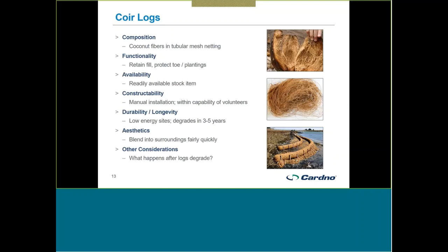I think one of the biggest considerations and potential downsides for their use in certain situations is their longevity. They are a natural material, and I've seen them last maybe up to 7 years, but they're looking pretty ratty. I think 5 years, maybe 3 years on the short end. 5 years is probably a pretty good rule of thumb about how long they'll last. And if you subject them, even when they're new, to high wave energy environments, they're not as durable as some other materials.